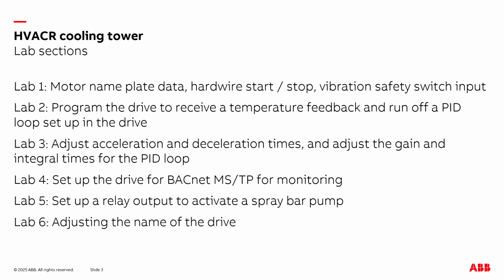In lab 2, we're going to set up the drive to receive a temperature feedback signal directly into the drive and allow the drive to run autonomously off of that signal, what's called the drive's internal PID loop. In lab 3, we're going to adjust the acceleration and deceleration times in the drive and also adjust the gain and integral times in the PID loop.